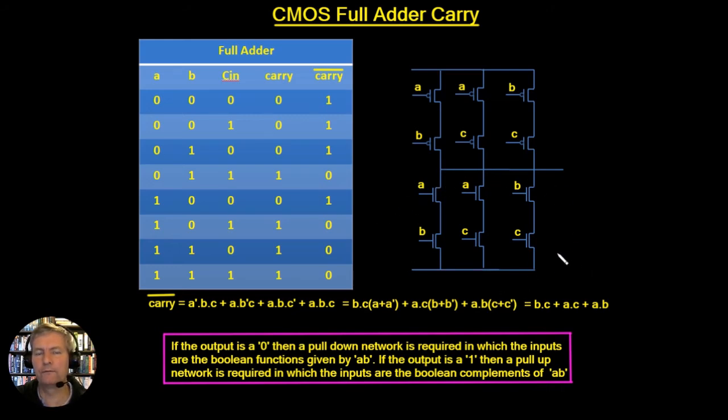Now, as we've seen whenever we did the NOR and the NAND gate, in order to go from this pull down network, which is the NMOS pull down network, to the CMOS pull up network, what we can do is we can take the series combinations and make them parallel, and we can take the parallel combinations and make them series combinations. And that's just what we've done here.